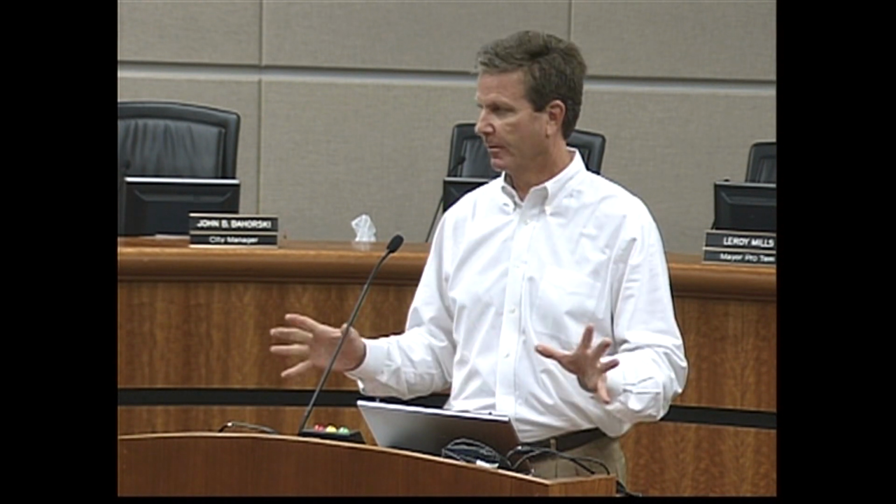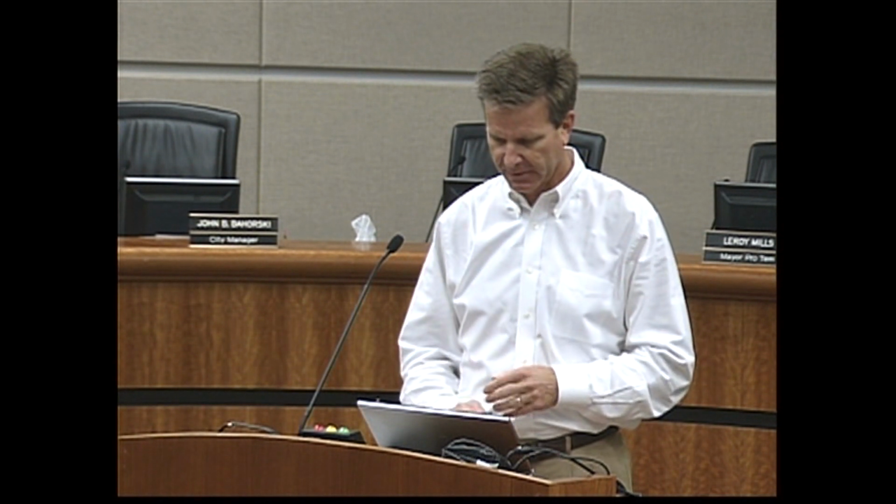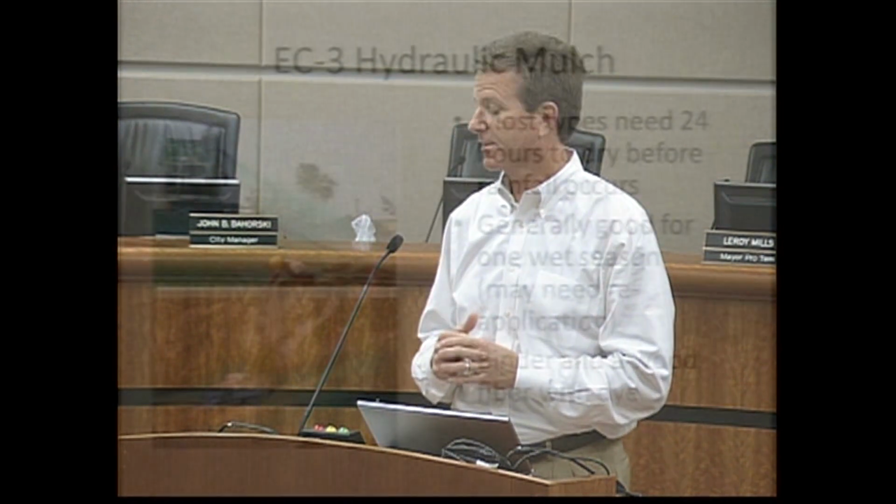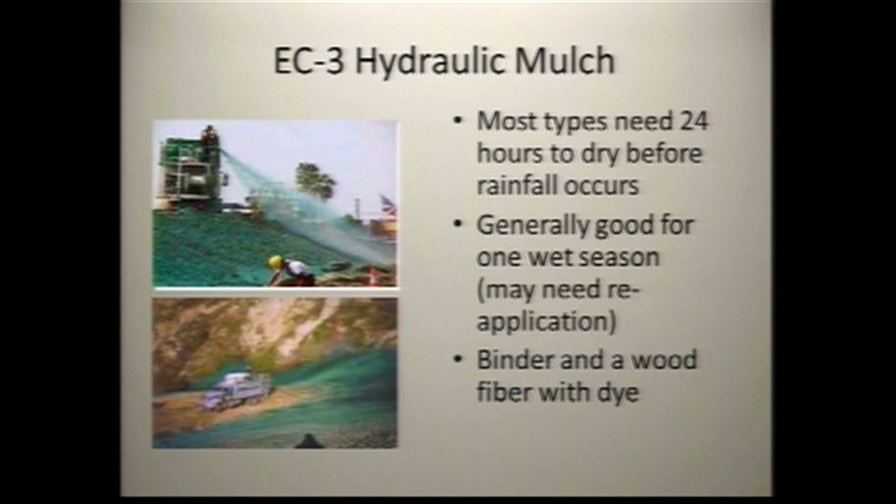Of course, have all the sediment controls that we'll talk about in a minute as well. And they'll be in compliance with the permit that way. Kind of the next step up are hydraulic mulches. These will last several storm events. And these would be used in areas where you're maybe not going to be working that area of the site for a couple months, and you want to be able to get through 6 months, say, of the rainy season.